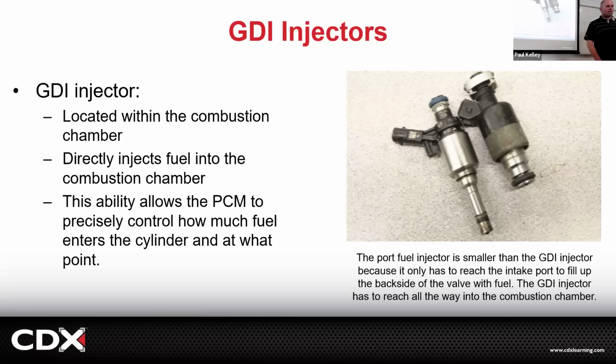So for example, if you had a Teflon seal failure, think about this. What would happen if that seal failed and it's poked into the cylinder and it's exposed to compression? I have seen it. I had one come in, and when you ran it, it would go pop, pop, pop, pop, and I checked compression on that cylinder and it was low. And I was like, but I can hear a noise. And so I was thinking it might be that seal.